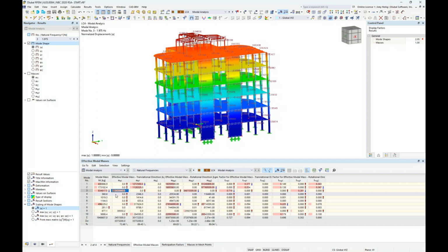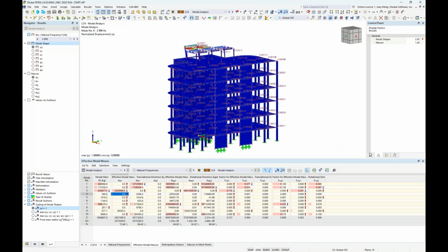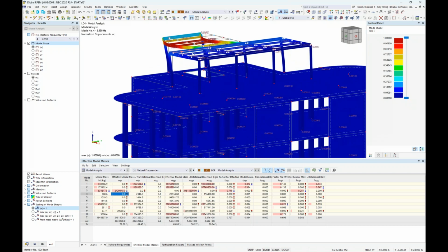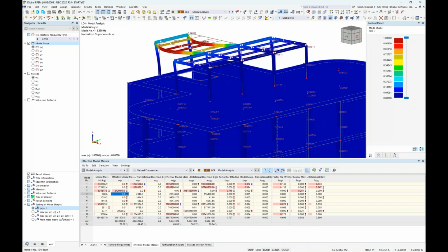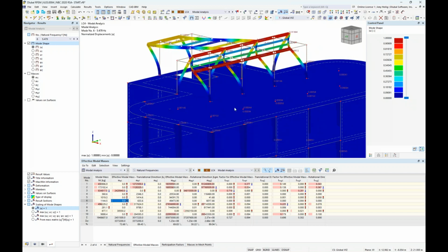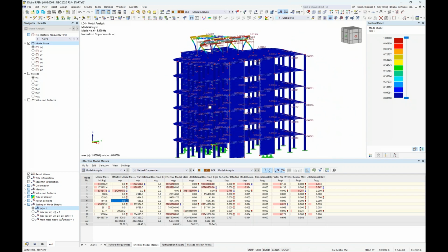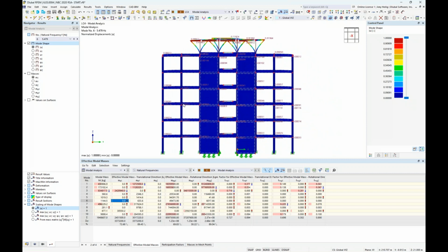Alternatively, if we take a look here at mode shape number 4, for example, you'll notice that really not much is going on with a majority of the structure. Rather, we're seeing a response up here for these smaller steel members only. Same concept with mode shape number 5 and mode shape number 6. So we usually term these local modes, where again, there's not much mass participation, but we're seeing a response for just maybe a few members. So I'd really like to eliminate these local modes in my calculation.